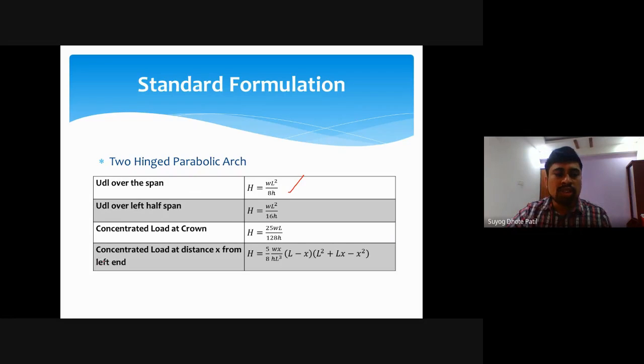In the basic beam problem we have considered shear force and bending moment, because all the external force is resisted by shear force and bending moment. Whereas in the case of arches, whether two hinge arch or three hinge arch, the load is resisted simply by horizontal thrust only.